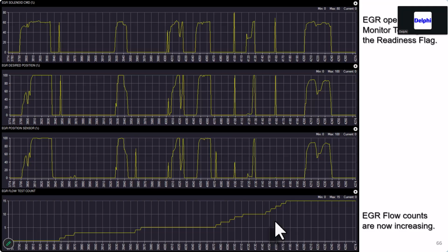That's exactly what I'm working on in this Silverado. What wound up fixing this car was a PCV valve and cleaning the MAP because of the vapors we're getting up in there. So my point here is, ask yourself, does it work normally? If the EGR is not open at all, then you're not going to run the readiness test. You're going to run other tests, and it's going to say, hey, EGR, there's something wrong with it. It's not even opening. But if you can see it opening like it is on the left-hand side of the page, you met some criteria to make it work.